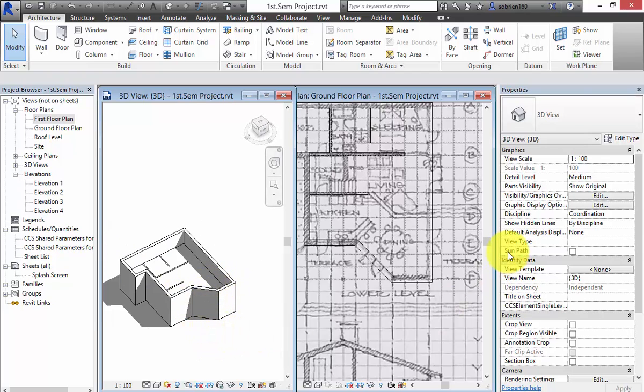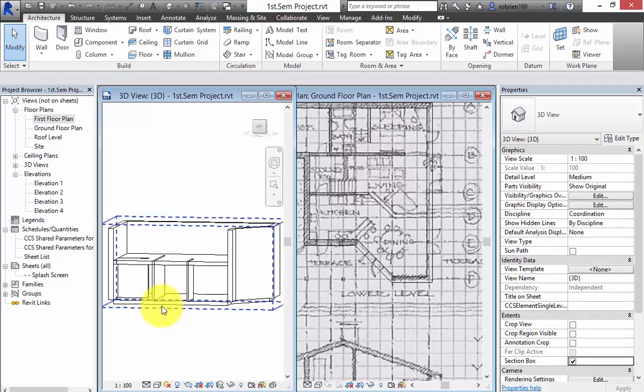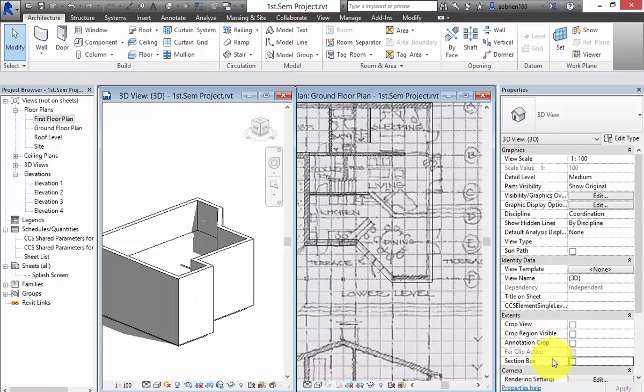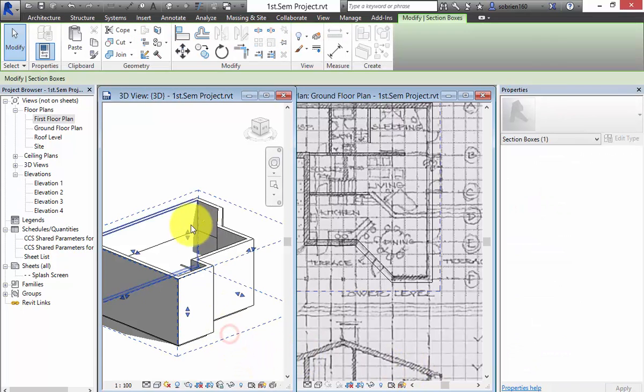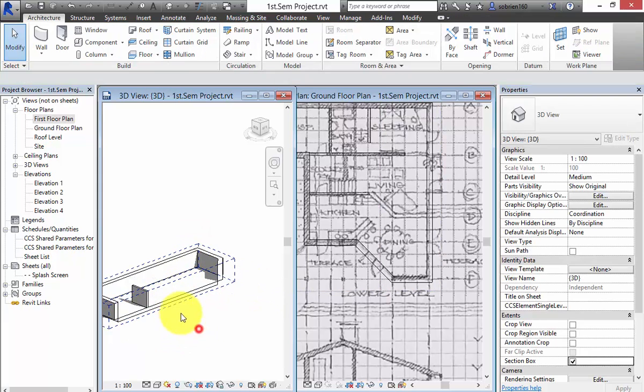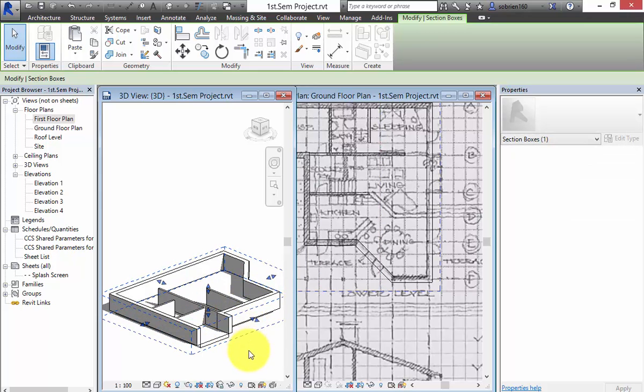What we can also do now, just to give you a little bit of the fun stuff in Revit, is we can put it on a section box, which is this little box here, and now we can take a slice through the building, and we can see what's going on inside it, like that. How did you do that? It's just if you don't select anything, so double escape everything, come over here, you've got the properties of the 3D view, and go down to extents, section box. You can click it on or you can click it off. Oh, section box. So this is a box that you can just stretch down through the building, so you can really focus on one element of the building to make a three-dimensional drawing of one element if it's helpful in terms of construction and so on.